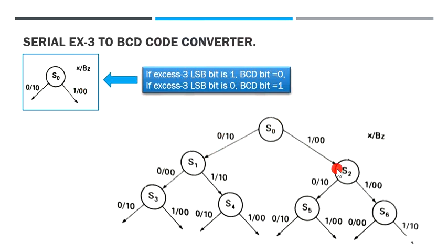So that is S0. The second XS3 input bit causes a transition from S0 to either state S1 or S2, to some new state. So this process will proceed. If I consider this to be S1 and this one to be S2, from S1, again if it is a 0, you can have a transition to 0 itself, and if it is a 1, you can have a transition to 1. Or if it is a 0, it can be 1, or if it is a 1, it can be a 0. So to observe how we have got this, we need to look into the